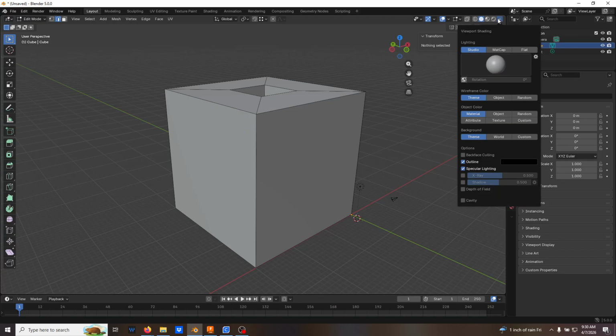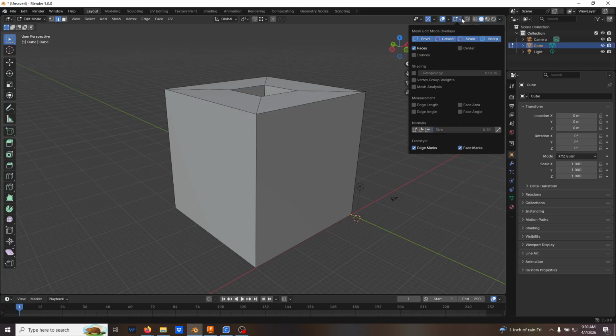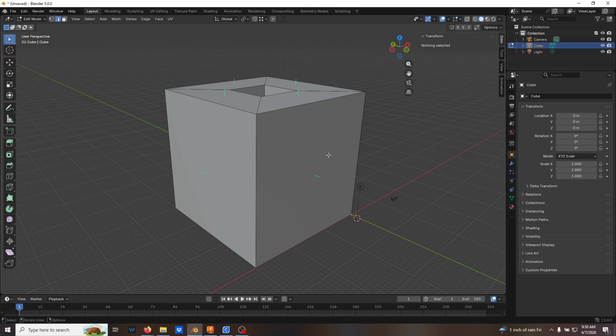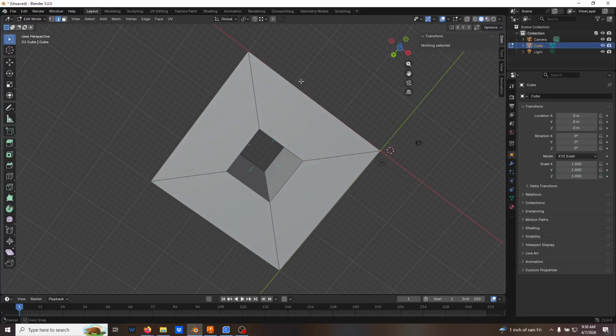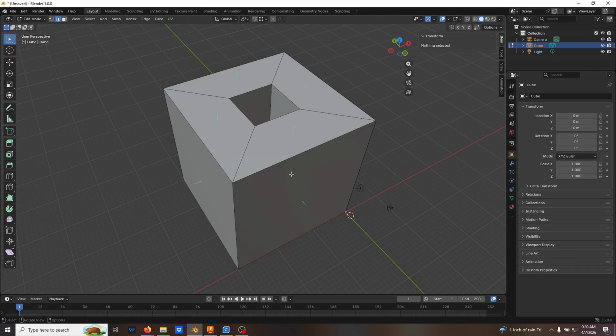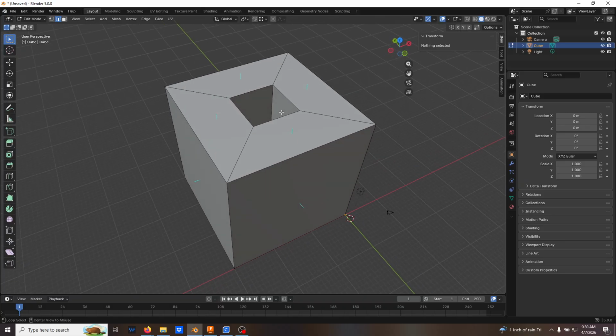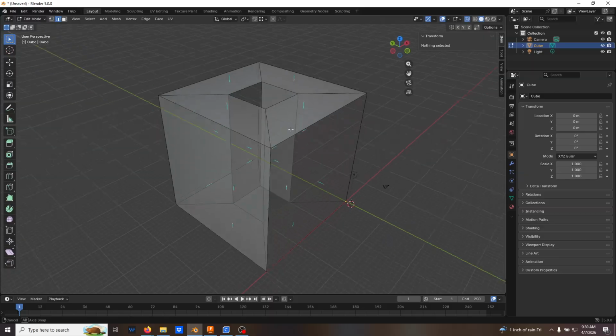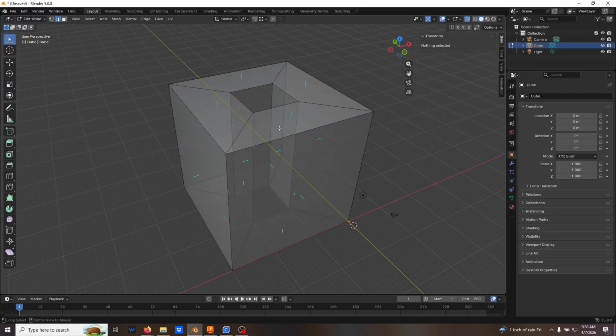So I'm going to go over to this button over here, not this one, and you'll see this highlight normals. The idea is that these faces have directions, and it's important for how these things go. This will show all of my face normals. One of the things you have to worry about when you're creating solids from meshes is that you imagine wrapping your solid in aluminum foil or something like that. Your normals want to point outside, and then I can do Alt Z to turn it transparent, and you can see all my normals are consistent.